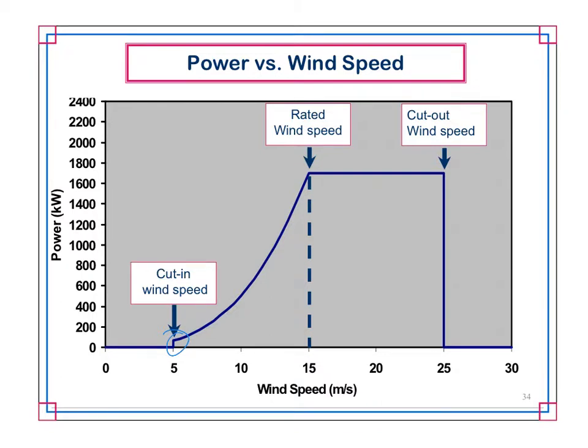At 15 meters per second, it's going to continue to ramp up, and you'll notice this curve is an exponential curve. This is that cubic of velocity, right? So you're getting slight changes in efficiency, but not that dramatic. The reason being, as I mentioned, the angle of attack for the blades is set up to do maximum capture of wind.